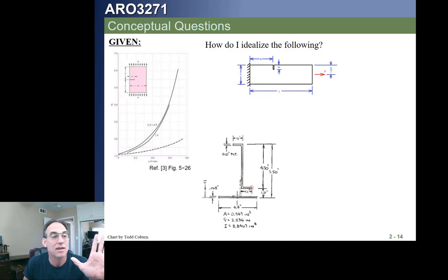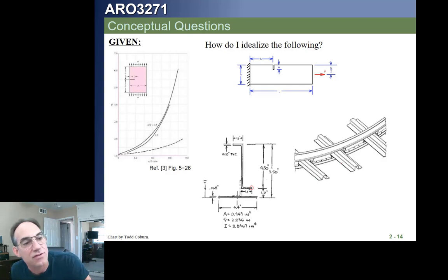If this part is in tension, though, then all the stress on it is the same, and our B dimension that we need might be 1.1 plus 4.5 plus 1.1 minus the thickness, because actually it's going to be 1.1 minus half the thickness plus 4.5 minus the full thickness plus 1.1 minus half the thickness. So we assume that that whole part is effective and then calculate that width. So this is the way we're going to do this.